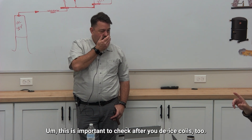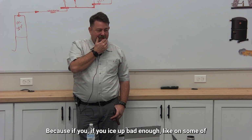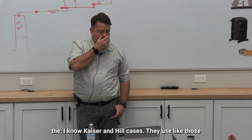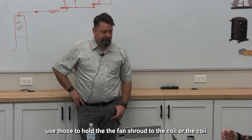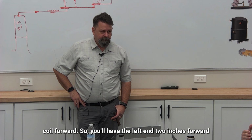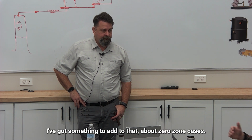This is important to check after you de-ice coils too, because if you ice up bad enough, like on some of the Kaiser and Hill cases, they use those plastic clips that hold your body panel to your car. They'll use those to hold the fan shroud to the coil or the coil to the back wall, and that ice will break that clip, push the coil forward. So you'll have the left end 2 inches forward and the right end where it's supposed to be, and you won't even notice.